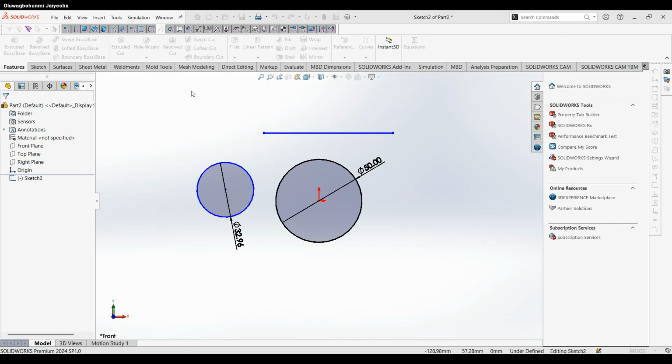So from the arrow to the list, I'll select A and plus. I will not type B. I will select from my global variables. I'll select B. So I can press enter now. You can see it computes A plus B for me, that's 35. So I've set my parametric equations for my design for the particular question I'm working on. So you press enter. Okay, click on OK.